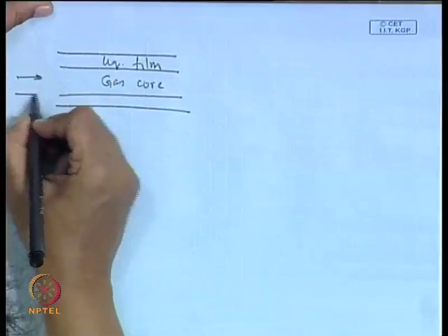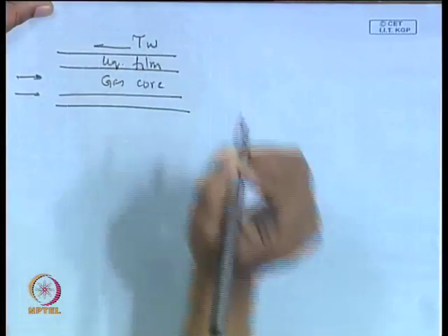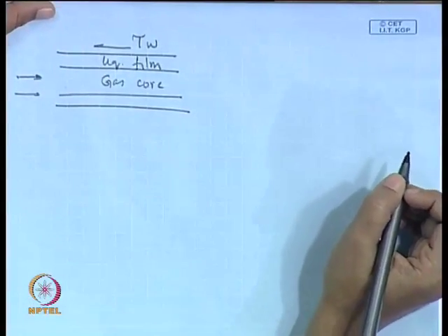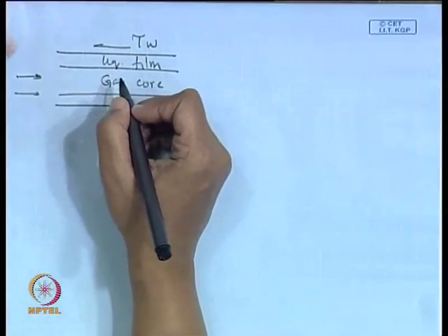So, for such an annular flow situation, if we can represent it, it is sort of this. Very straight lines I have drawn. This is a gas core, this is a liquid film. If flow occurs in this particular direction, then wall shear stress will be in this particular direction, and there will be a tau I, the interfacial shear.